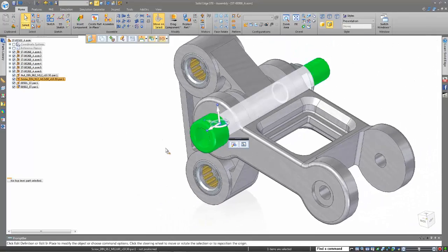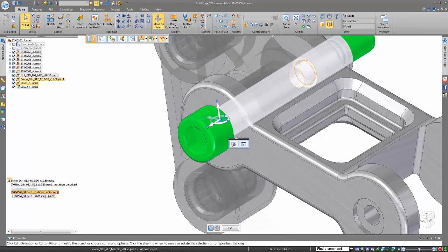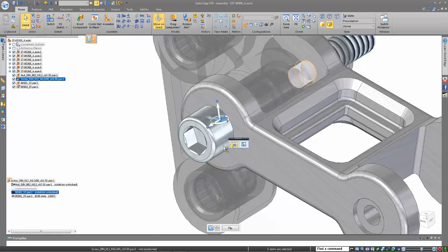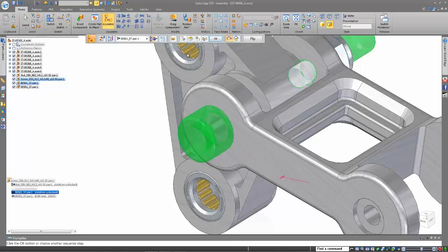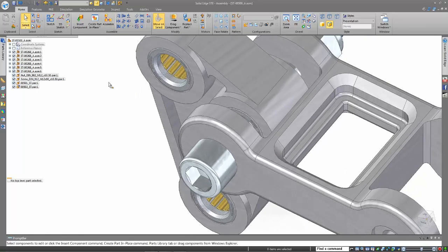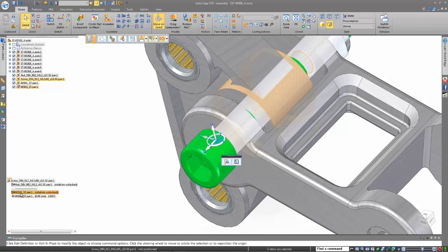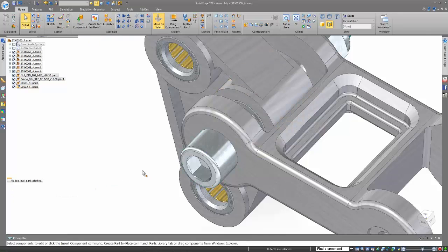Same thing here for this screw. You'll see that the screw has a relationship with part 501, an axial relationship. If I wanted to modify what part it is related to, I can change that with this nice handy quick bar up here and say, no, let's align it to this component instead, and that quickly it allows me to change that, and now you'll see that it is aligned with part 502 versus 501.